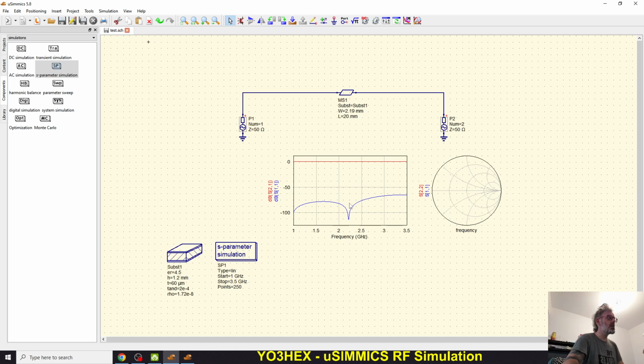You are aiming a lot for this because in real life you will not have the exact 2.196 millimeter width. You will vary a lot. If you are not going to go for an impedance control type of substrate, your FR4 substrate will vary a lot.